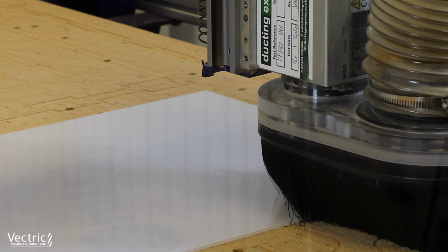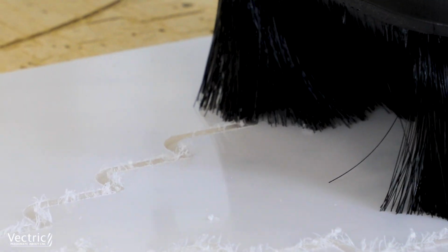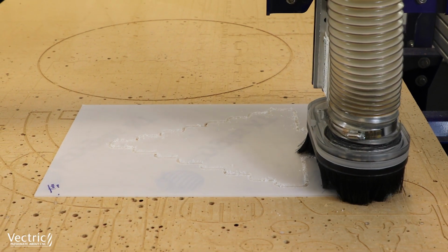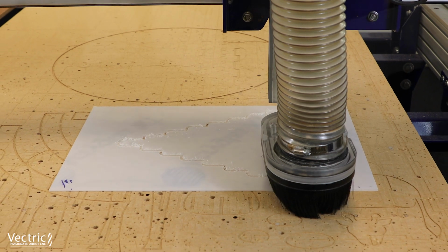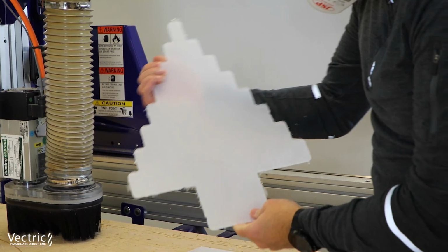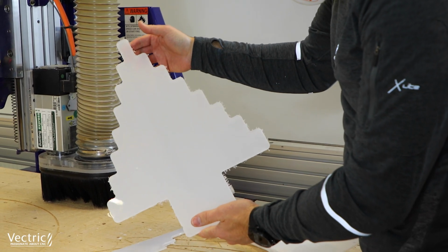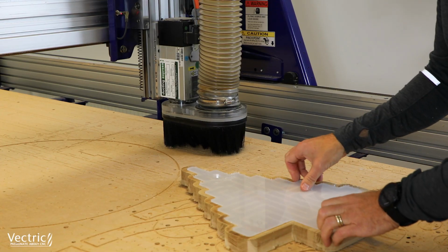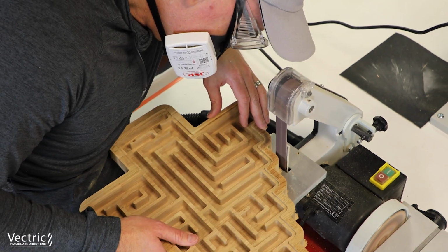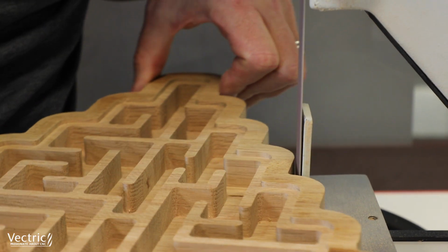Now we'll go ahead and swap out that material. We put our acrylic down. I double-sided taped it to our CNC and held it in with those very small tabs. This was a really fast tool path and didn't take long to cut at all. And as you'll see in a second, there's the remainder of one of those tabs at the very top of the tree where the star goes. I just needed to push that forward and it popped right off. It fit perfect, but it was a little bit small, but that was okay because I wanted to be able to take it in and out if I needed to.